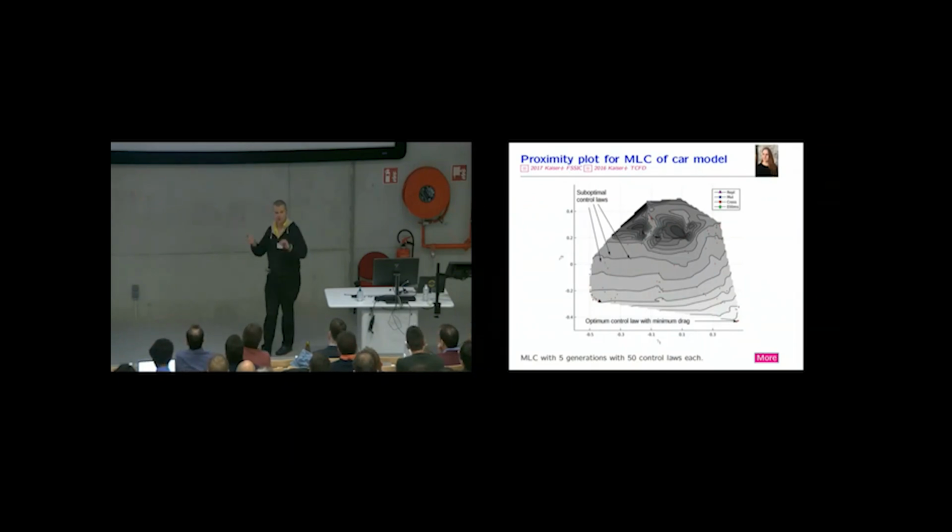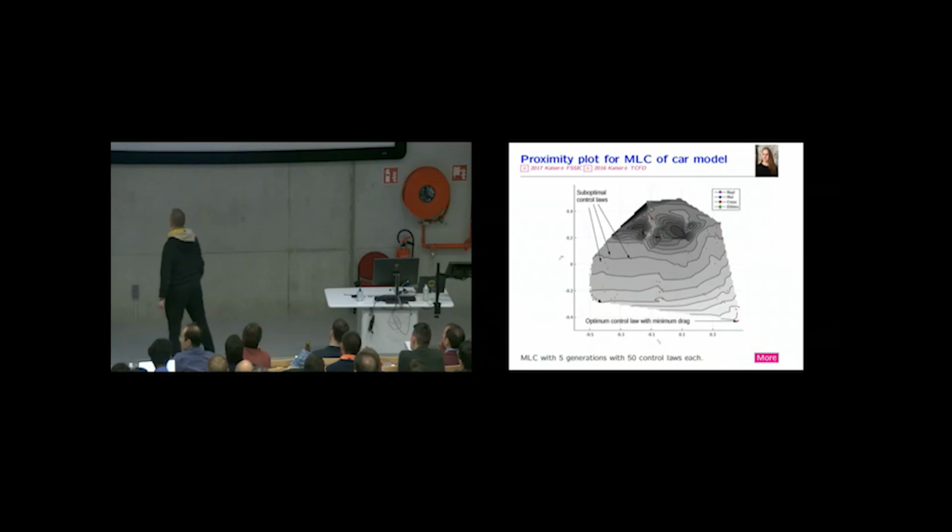We would expect typically a minimum in the inside. It turns out that this gamma 1 here corresponds to the frequency. This is high frequency, this is low frequency. This gamma 1, gamma 2 happens to correlate with a duty cycle. This is low duty cycle, small duty cycle. This is high duty cycle. So the best thing is to have very high frequency with a very small duty cycle, but this turns out to be the limit of our actuator performance.